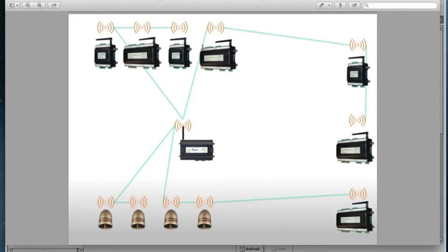So JACE goes out and communicates to devices, and you can see in this case we have 4 direct children to the JACE. Each of the children are responsible for 1 to 10 devices. Each coordinator and/or device can communicate to up to 10 children. So the JACE can have 10, each of the 10 children of the JACE can have 10, and it keeps going down. So you can create a very broad and deep network.